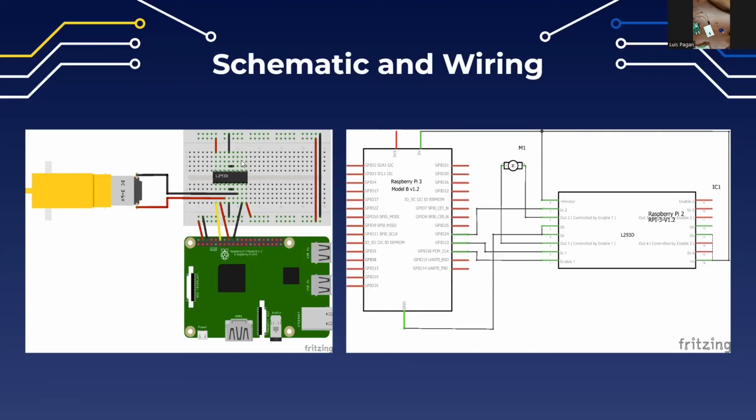In any case, you don't want to have wires always going on top of a board, going across the board. If you can simplify the route that the current has to take, it's the best practice, just to make the wiring cleaner and easier to debug visually.